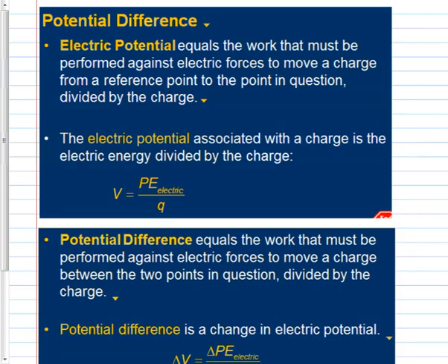If you think of a battery, it has two terminals. If it's those little square 9-volt batteries, what it literally means is between one terminal and the other terminal, there's a difference of 9 volts. It doesn't mean one of them is 0 and the other one is 9. It can be if one of them is grounded, it's 0 and the other one is 9. But I could hook another one up to it. So one goes from 0 to 9, the next one goes from 9 to 18. It's a difference of 9.